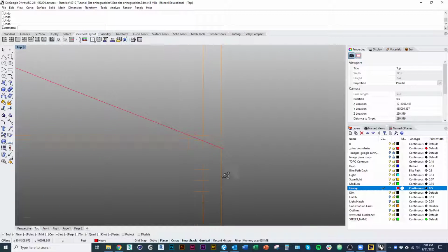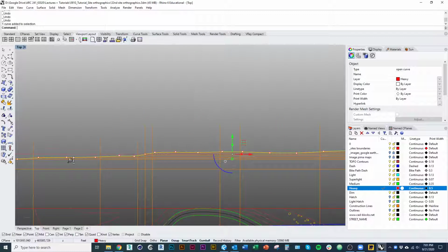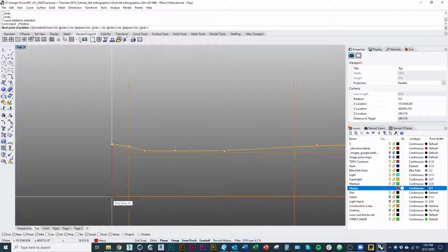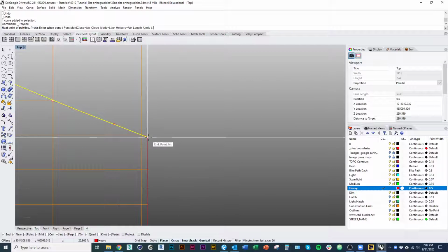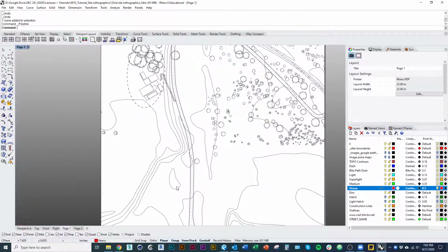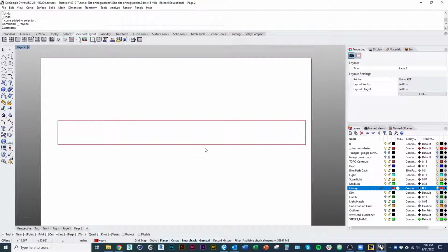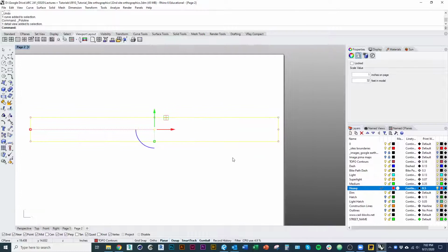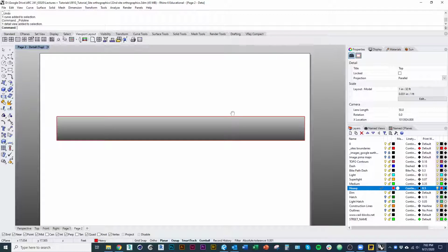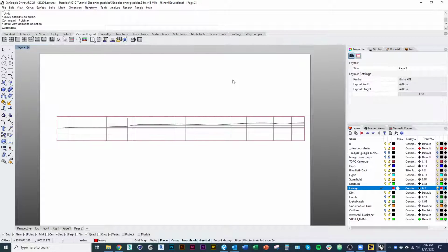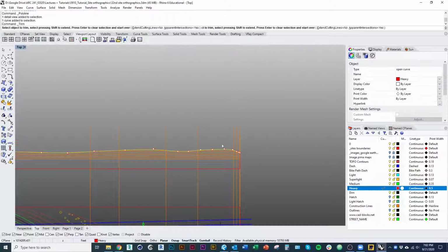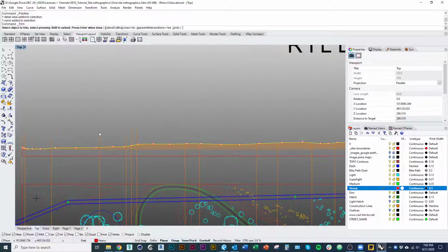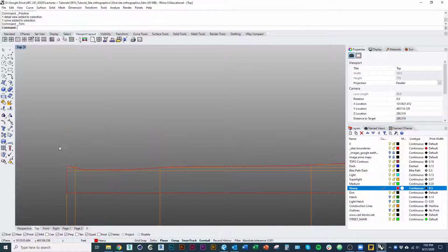Vector to the edge of my section. There we go. That's my section cut line. And obviously, I'd want to continue that around the outline so that it would look right. Section going on here. Lost where we had it. That's the thicker line, and we can still see the section lines. I would be inclined to take that section cut line and just trim away the extension. That's not really helping us understand it.